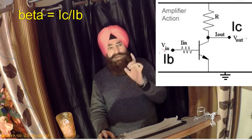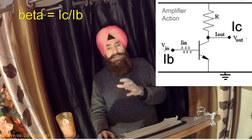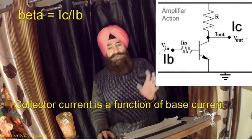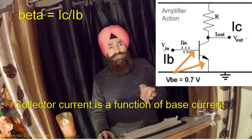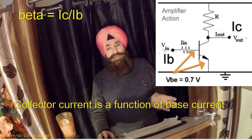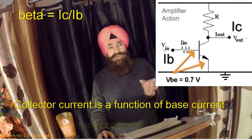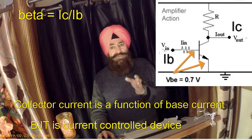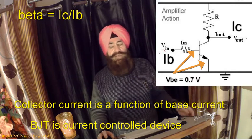The collector current is controlled by the base current, not the base emitter voltage, which is around 0.7 volt. So as the base current controls the collector current, the transistor is called a current controlled device, because the collector current is a function of the base current.